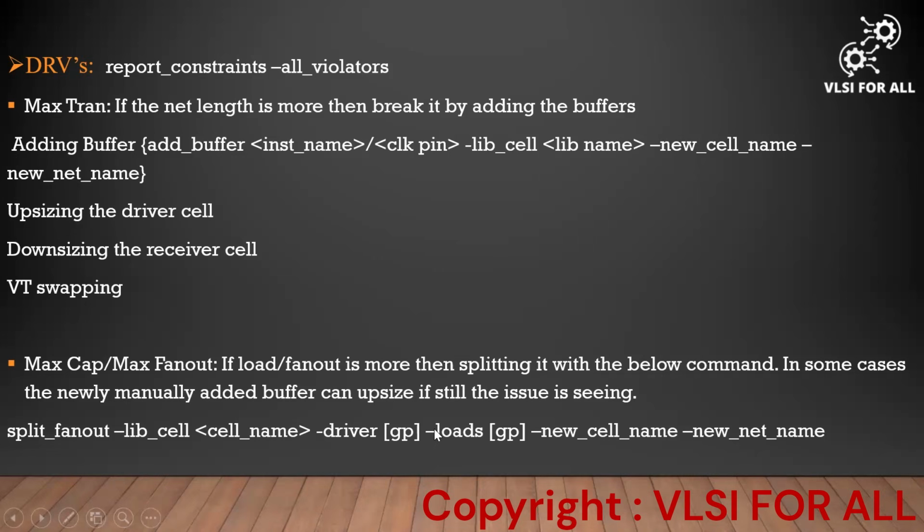In some cases, even after splitting the fan out, we'll see some max cap or max fan out issues. In those cases, the cell which we added for splitting the fan out, we can upsize. Like I mentioned here, in some cases the newly manually added buffer can be upsized if the issue is still seen.